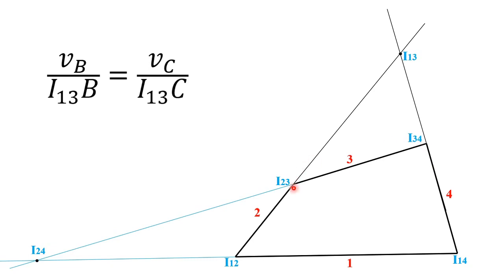So we have two velocities, velocity of B and velocity of C. You will be given the velocity of B or enough data to determine the velocity of B. In all questions, you just check your relative velocity method questions. You have the same thing. The first step is the same, because we have to find VB. First, you have to draw the space diagram, and you can also find the input velocity VB. Okay, so you'll get VB.